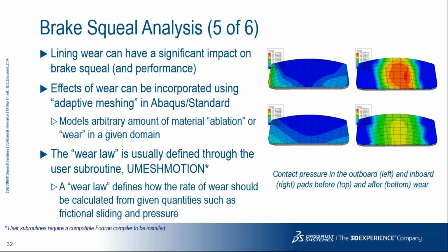And again, the lining wear can have a significant impact on brake squeal and its performance, because it affects the noise generation through the contact condition between the linings and the rotor. In a dynamometer test or a vehicle test, brake linings have to be burnished before they can be used for testing.